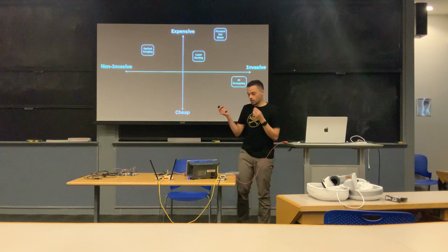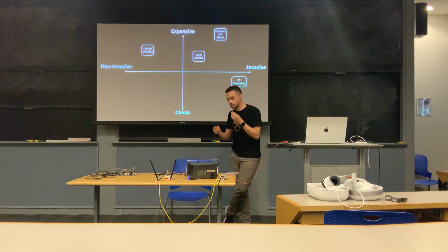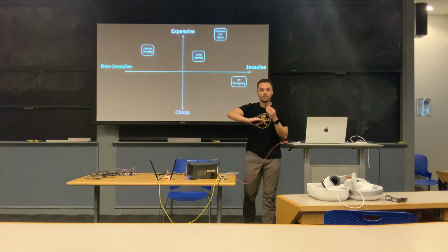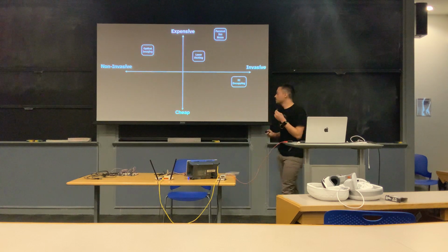Next is decapping. So we have these chips. You've probably seen some chips around. We just saw some chips. Actually taking them and decapping them, so taking off that epoxy layer to unveil the silicon beneath it. That's chip decapping. Really cool stuff.